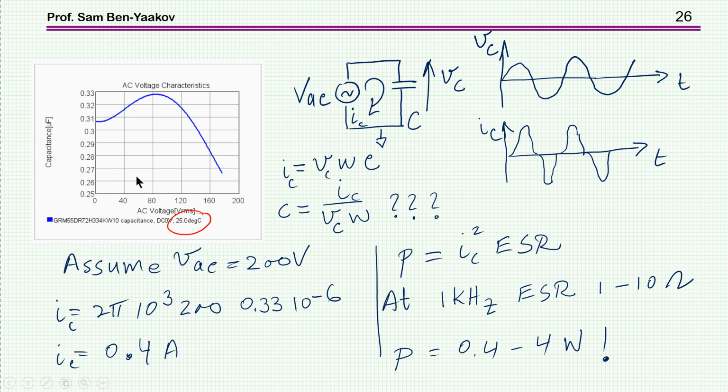Now, leaving alone the question of the sensitivity to AC, there is a major problem here from the theoretical point of view. Because if you drive a capacitor with, say, a sinusoidal waveform, say the voltage is sinusoidal, well, that's as sinusoidal as I could draw here. Now the current will not be sinusoidal if it's a nonlinear capacitor, so it'll be something like this.